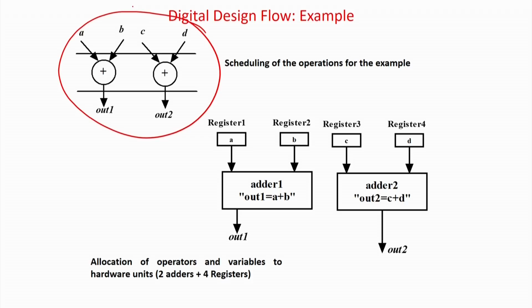This is actually called scheduling. High level synthesis means, first, the scheduling process. You have to do A plus B, C plus D. Do I need the answer in one step or in 2 steps? If you need the answer in one step, then both the adders have to be scheduled in step 1, because there is no dependency. Now fine, this is one schedule.